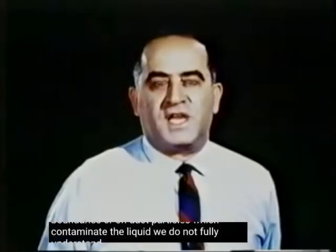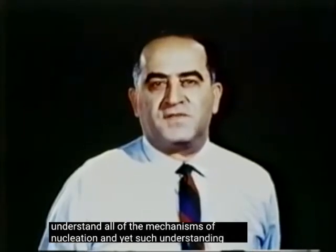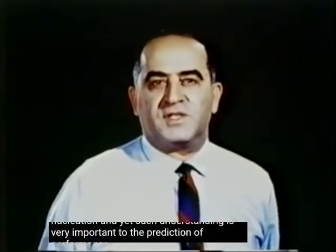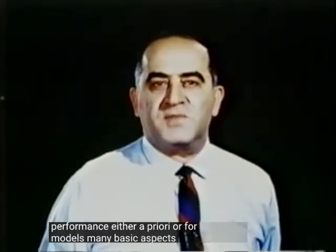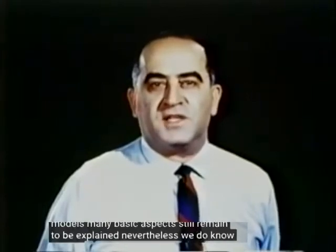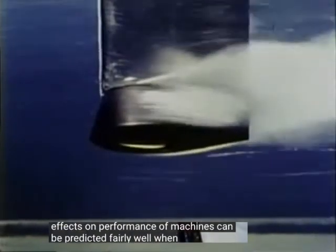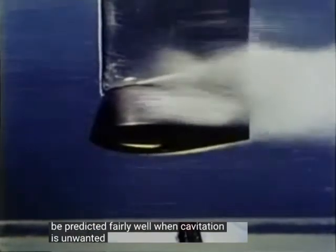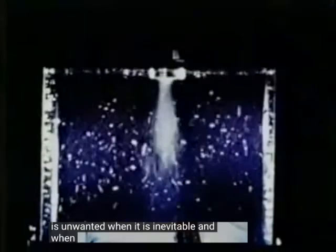We do not fully understand all of the mechanisms of nucleation, and yet such understanding is very important to the prediction of performance either a priori or from models. Many basic aspects still remain to be explained. Nevertheless, we do know a great deal about cavitation, and its effects on performance of machines can be predicted fairly well when cavitation is unwanted, when it is inevitable, and when it is sought.